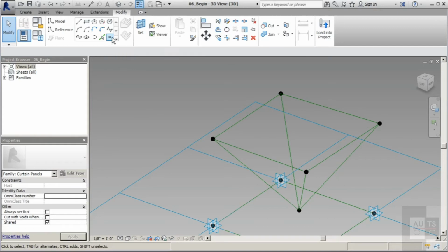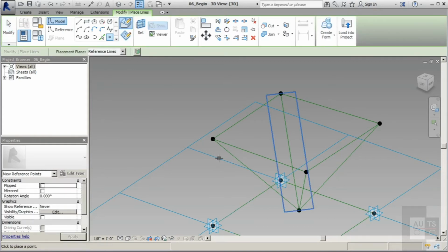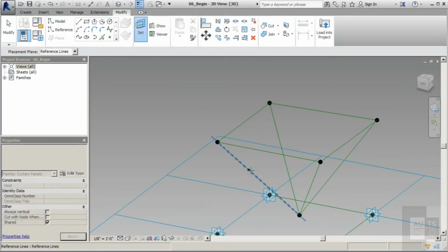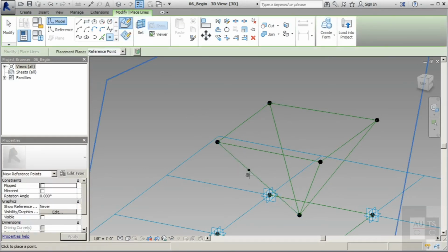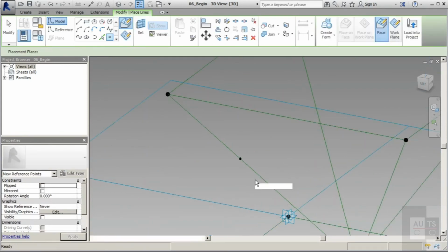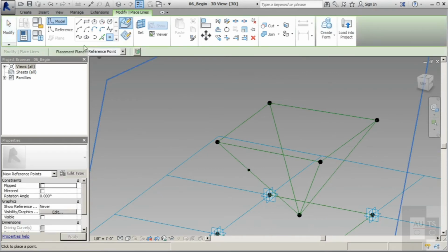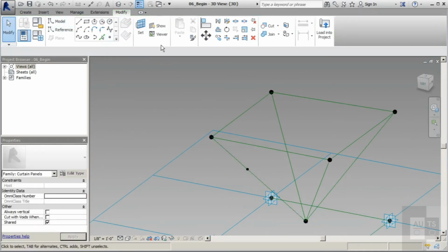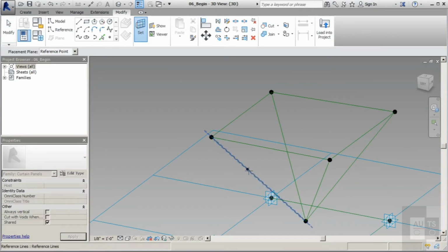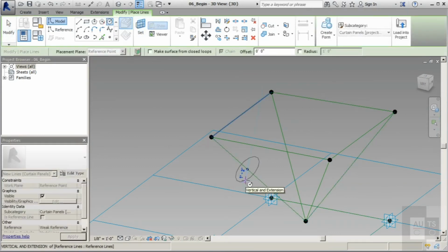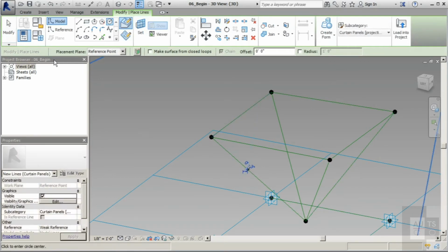So again, we'll do what we did before. I'm sure we have a good understanding of how this works now. We've done it quite a bit, so we'll go ahead and place the point. We'll create our circle, making sure we snap on that center point. Looks like we need to make sure we get a model reference line. Actually, we need to set that line. So we'll go set, select, draw my circle, 3 inches, hit enter.